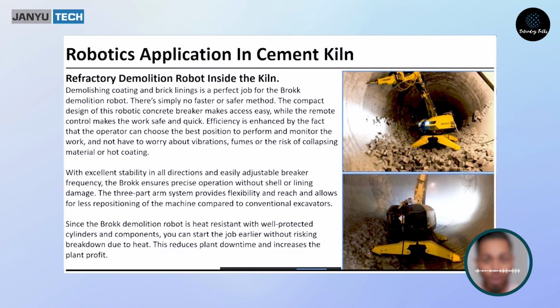If some kind of robotic system with a camera, monitored from outside, could do the inspection inside the kiln, that would help. There is always a risk when a person is inside the kiln in a small shutdown, because material can slide out from the cyclone area. There have been fatal accidents in that case also. So that is again a safety issue.